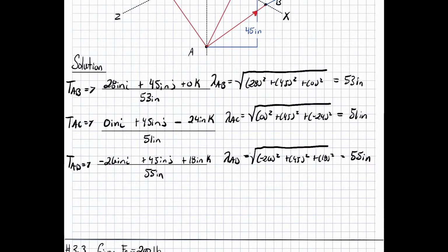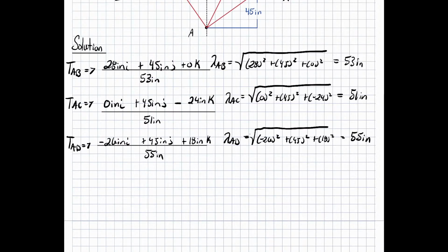Okay, so now we have our evaluations. We need to do our sum of forces. So sum of forces in the X direction, all equal to 0. Normally this is where you'd state your coordinate plane, saying like it's positive to the right or positive up. This is in 3D, and they gave us our coordinate plane, what's positive and negative, so we don't necessarily have to do that. But if you really wanted to be more detailed, you could say that's positive to the right.